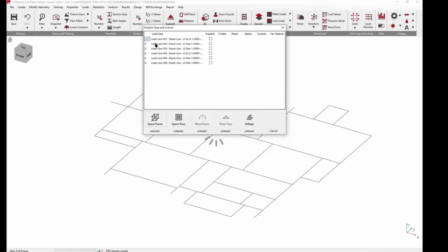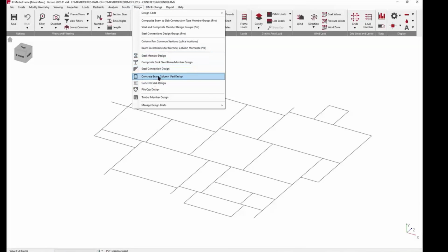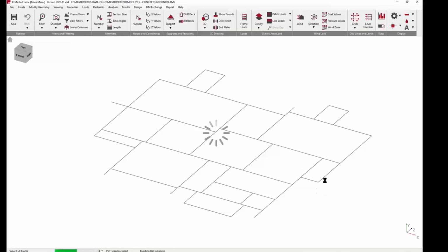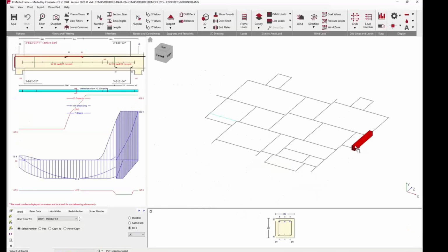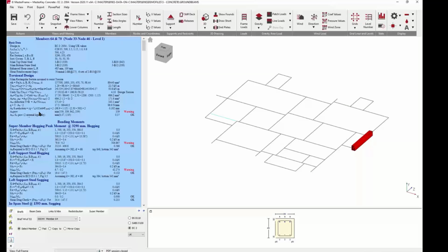If it's high torsion, it'll start to remove some of the main steel from the capacity design. There was quite a torsion in one of these, if I remember rightly. So you know you've got bad torsion when you suddenly find sidebars. But if I look at one of these and look at the results, you will see that there's a little bit of torsion being resisted.